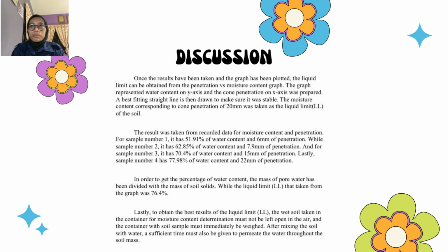For sample number 1, it has 51.91% of water content and 6 mm of penetration, while sample number 2 has 62.85% of water content and 7.9 mm of penetration.